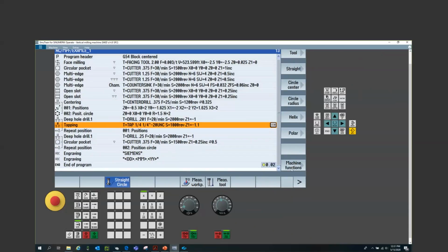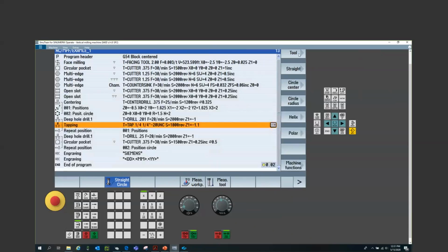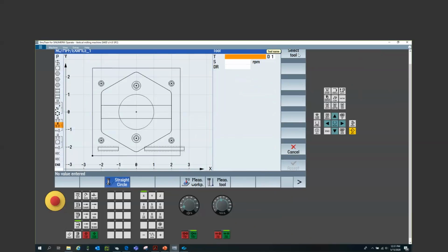Yeah. So you see that button up top, upper right-hand corner, says tool. That allows us to do tool changes without having to be in a cycle. Sets up our spindle RPM. And if you go through all of those screens, Steve had popped into one just before, there were the machine parameters as well. Pretty much everything you would need to set up proprietarily before the hobbing cycle, you could get to within conversational.